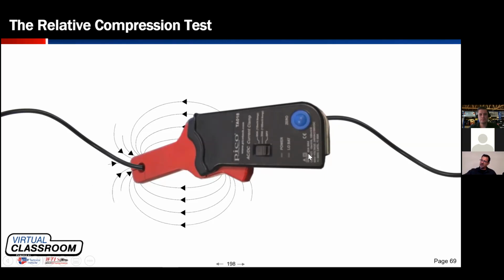So for instance, if you look closely here, this is a very poor resolution capture to see these numbers here, but this will give us a range, a conversion chart. And what it might state is for every 100 milliamps that flows through these jaws, 1 millivolt of voltage comes out.